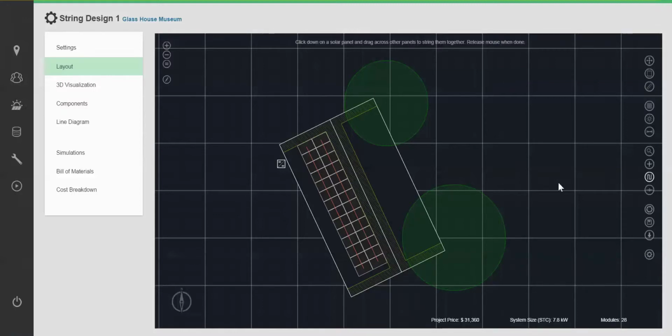Now I can click on the Connect icon to connect my strings to my inverter. You can also place anchors in your connections just like you would conduit runs. After connecting strings to the inverter, I can continue to add balance of system components.